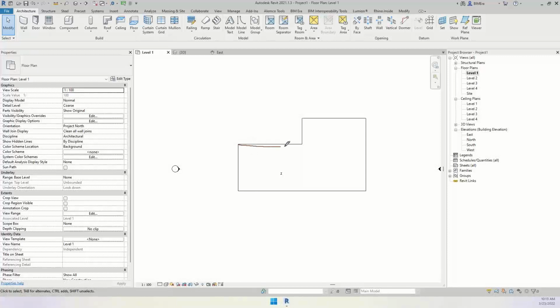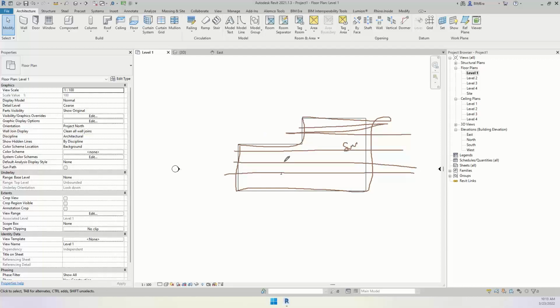So first we got the outlines of the floor, then we converted this outline into a surface, then created some isolines, then we split it using Geometry.Split with these lines and the surface. Then these individual surfaces will be created, superimposed on the floor, and it has to cut exactly as per the same, correct?